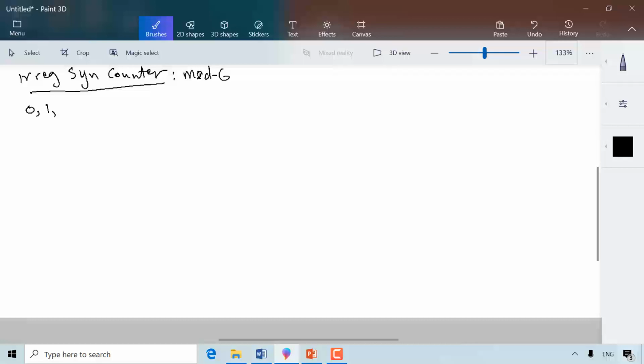It counts from 0, 1, 2, 3, 4, 5, and we stop at 5 because you cannot reach 6 or exceed it. Then we repeat 0. As we said in the intro, this is an irregular counter because it doesn't continue all the way to 7. So let's get into the very first step of the general design process of sequential circuits.